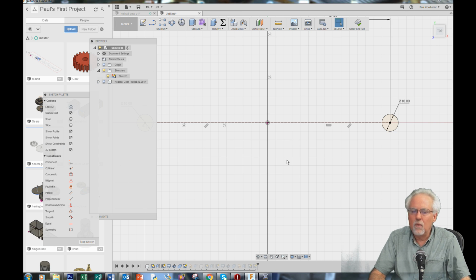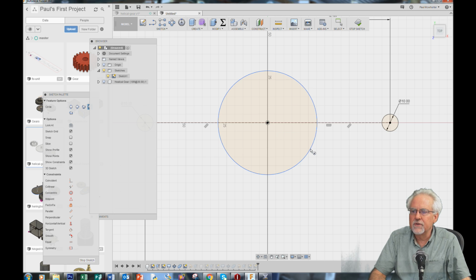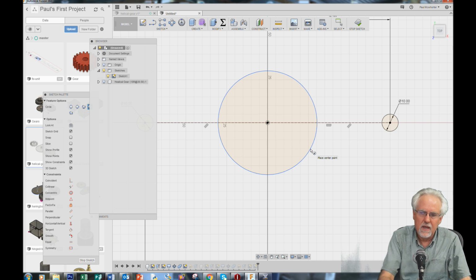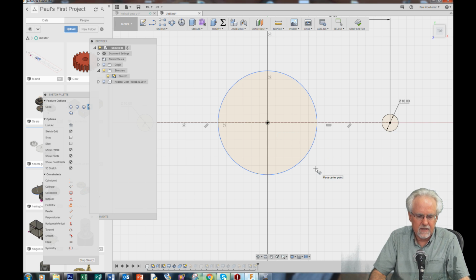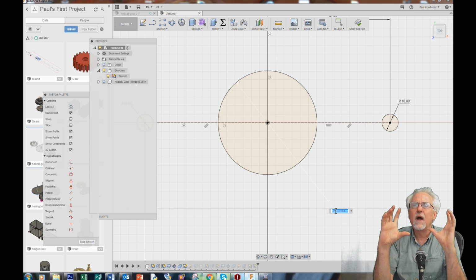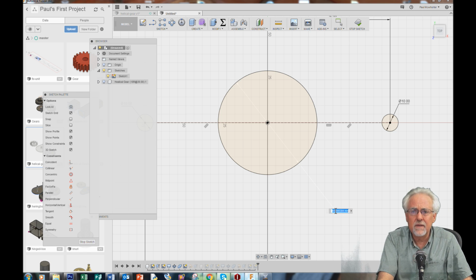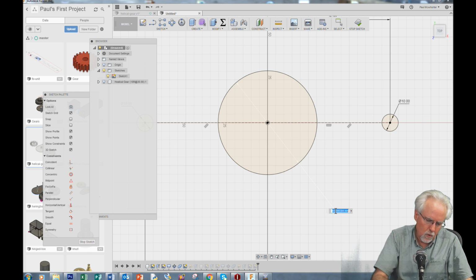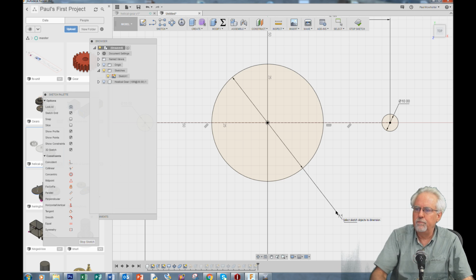All right. Now what I'm going to do is draw a circle. So I press C, come here, hover over, and draw the circle. This is going to be the big one. So I press Escape and then D for dimension. How big do I want that? I want that to be flush and nice underneath the big gear. And so what was the outside diameter of the big gear? It was 68.354. Enter. Boom.